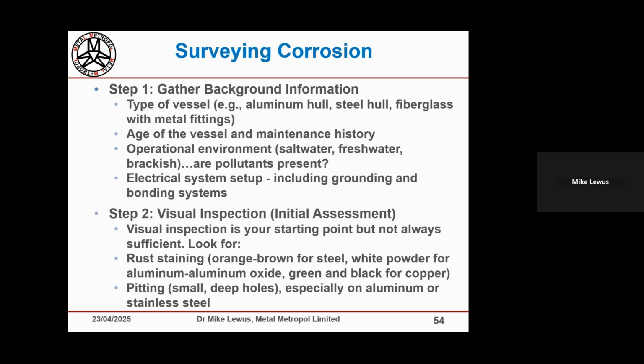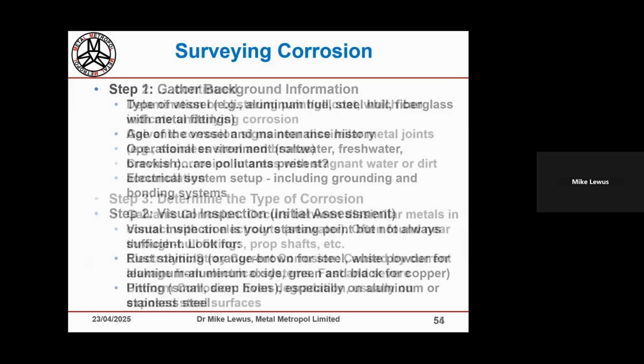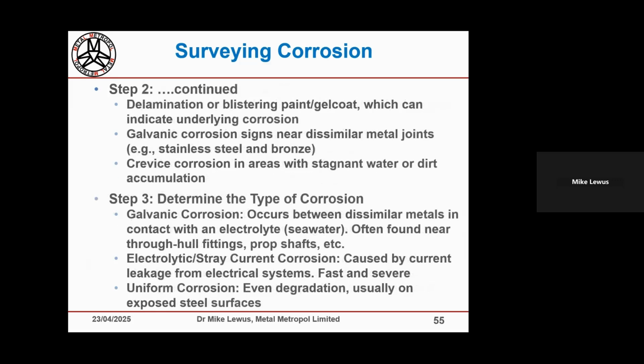But it may not just be those simple things. It could be there's an element of pitting. This is where you've got to make a decision if you're going to inspect something visually. In fact, I can move on to the next slide because there are other things here. You may not be able to see pits unless you remove corrosion debris. So a lot of what you do is going to be dictated by how critical the corroding parts are.